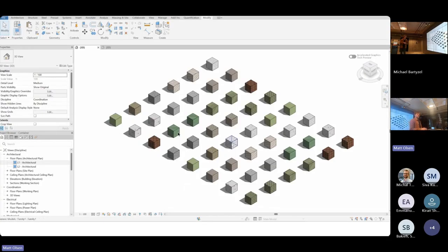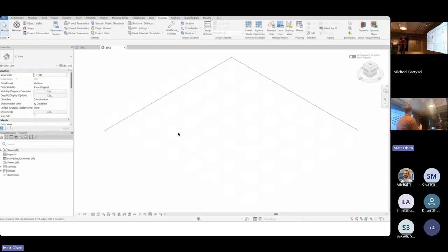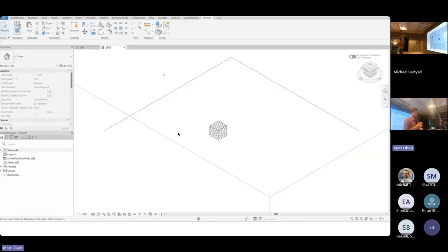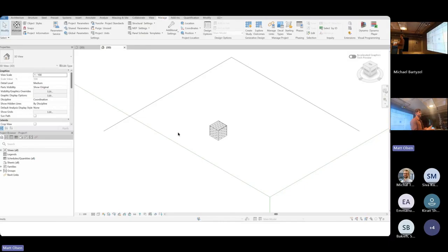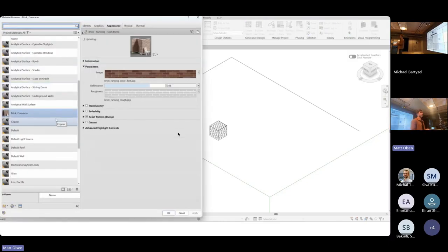In my previous practice, we worked around it by creating a container file with block families, each of which contained one single material, and you could just copy paste those into models. This required a lot of maintenance, and it's cumbersome because you need to open the model each time, and we needed to copy it across Revit versions. It's a workaround.